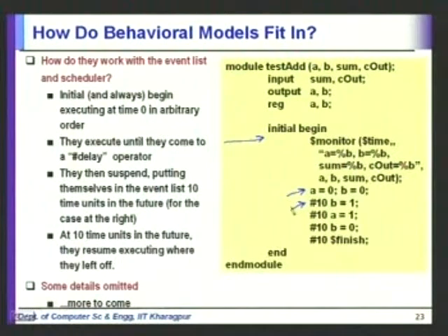Because Verilog is not just one procedure like this. There are several modules, and because this is hardware we are talking about, they are all there in parallel. But we have to simulate the thing on a single processor. So we have to treat them as concurrent, because physically in hardware they are all going to be really parallel, but in simulation we cannot have that. So we are going to do that serially, but we have to maintain certain guidelines so that the final outcome is consistent with the actual hardware.